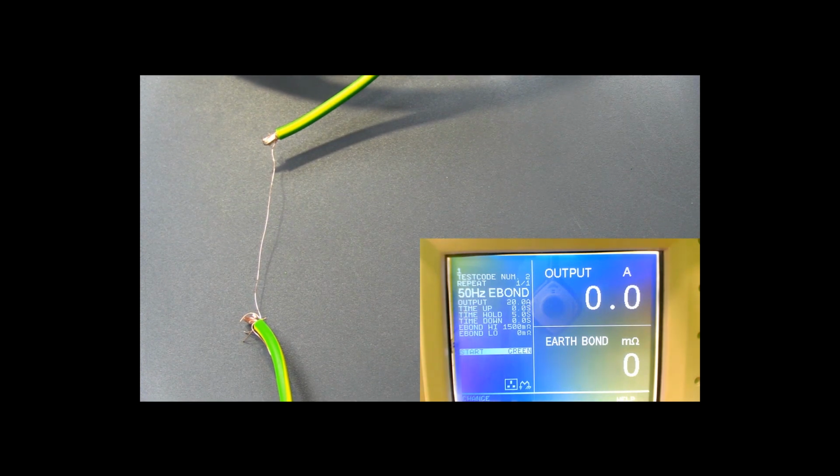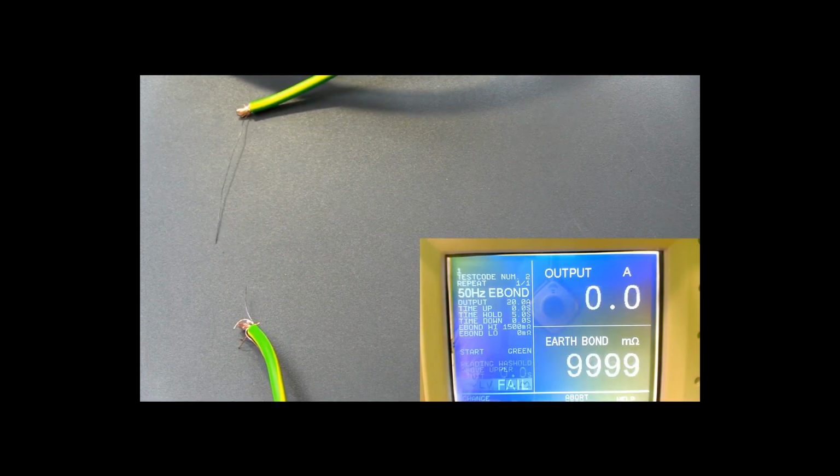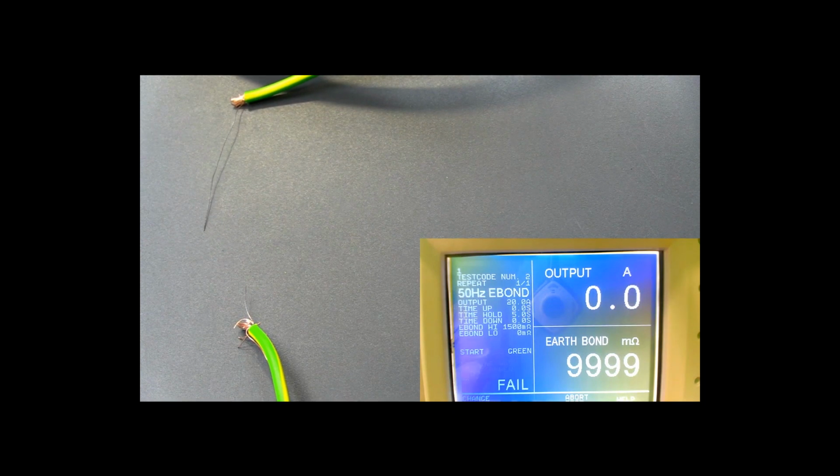Now, when we go ahead and perform it at 20 amps, we should see the resistance will be much higher because that current can no longer flow freely through the conductors. And hopefully what we'll see is the cable heat up and fuse due to that excessive heat. So let's go ahead and start the test away. And you can see almost instantly the cable got hot, the cable fused, and our test equipment picked that up as a failure condition. So that highlights why a bond test is a much better test on either a production or a type test environment to prove that you have a good earth connection.